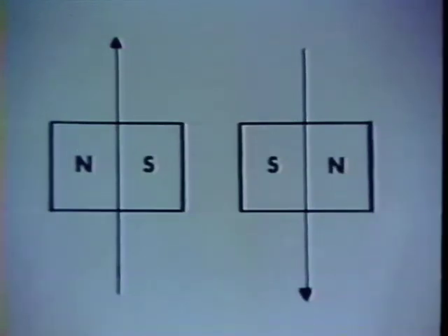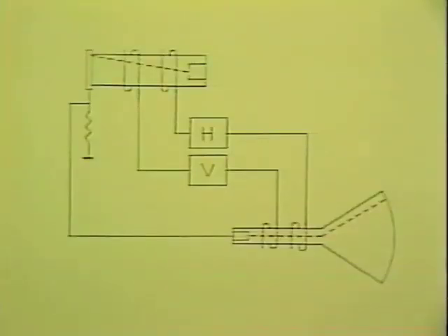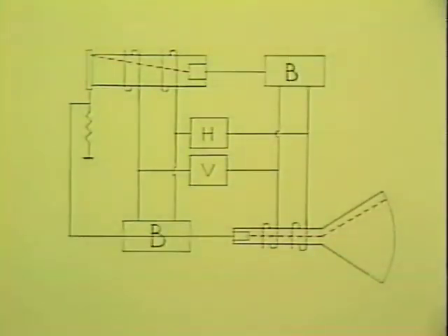We said earlier that the beam is blanked during the horizontal and vertical retrace periods. Blanking the beam is very easily accomplished. The signal from both oscillators to the coils is also fed to a blanking circuit. The only time this circuit operates is during the retrace period. The output of this circuit controls the operation of the electron gun.